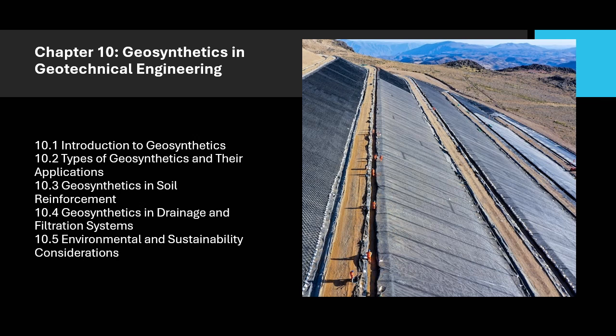Geocells are used for vegetative slope protection by providing soil stabilization and reducing erosion while allowing vegetation to thrive. 3. Soil stabilization for roads. In regions where soils are particularly soft, geocells help in stabilizing the soil, promoting vegetation growth, and enhancing load bearing capacity for unpaved roads.